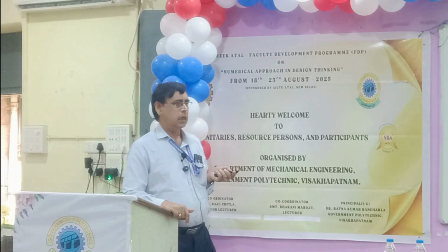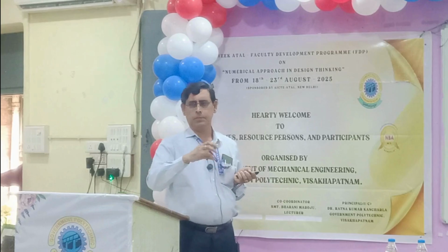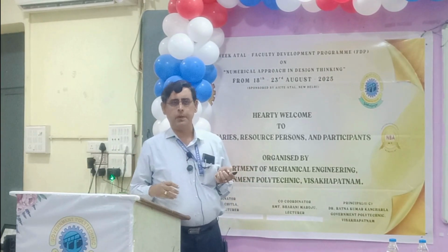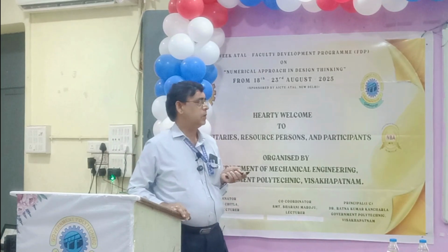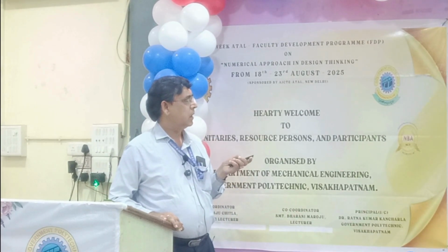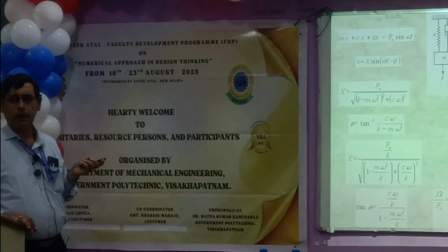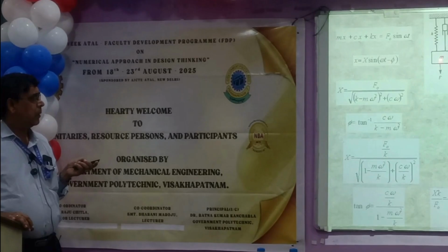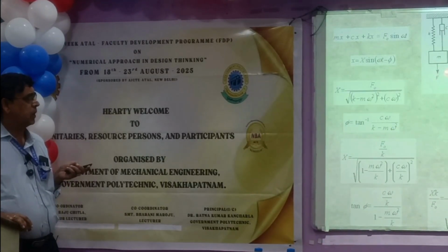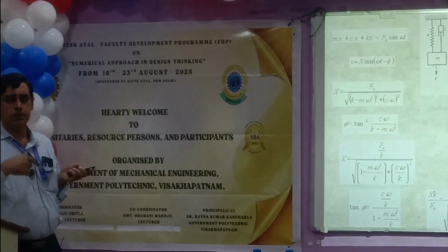In the case of forced vibration, in any vibration theory, it is always idealized as a spring mass damper system for mathematical treatment. That is more convenient to treat. Therefore, people use this model. The K represents the stiffness of the spring, C represents the damping coefficient, M represents the mass of the equipment, and force is what is being imposed on the equipment.